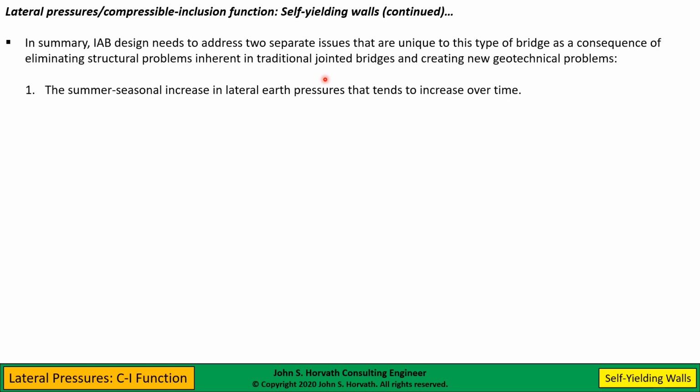Because most of those design pressure diagrams have been based on one cycle of thermal loading. It doesn't address what happens over 5 years, 10 years, 50 years. I mean, keep in mind, these bridges can have a design life of 100 years or more. So we don't look at the long term of what these pressures could be.